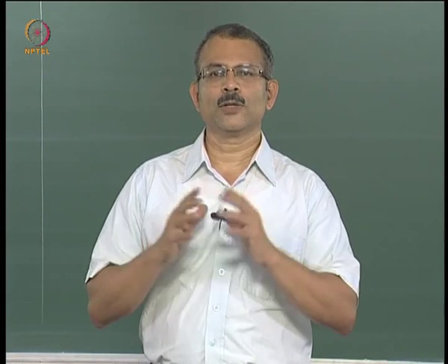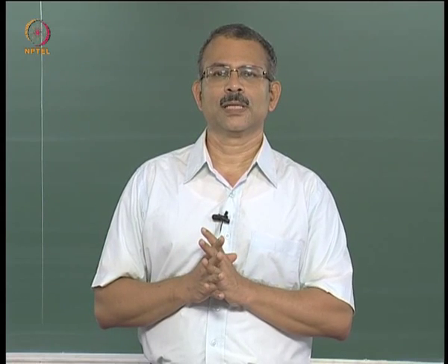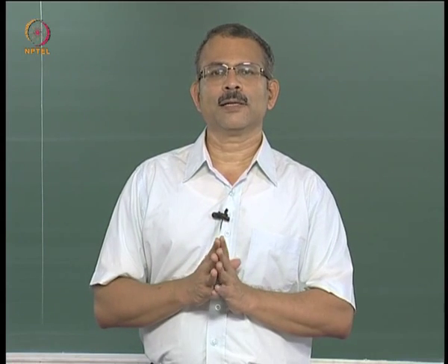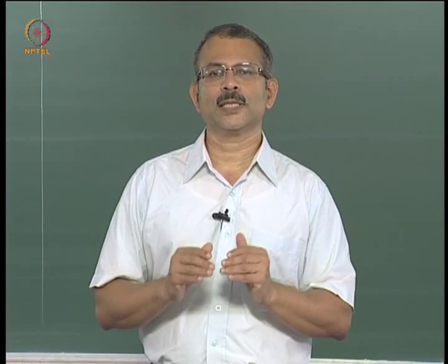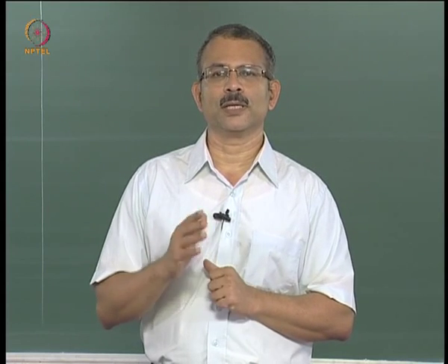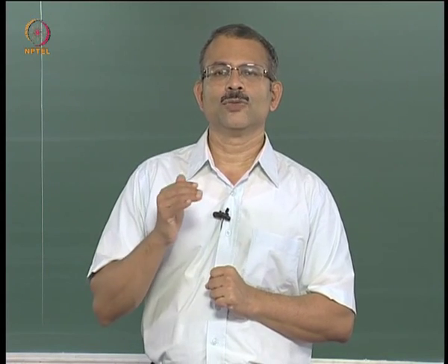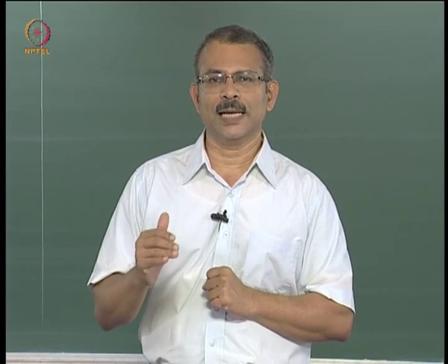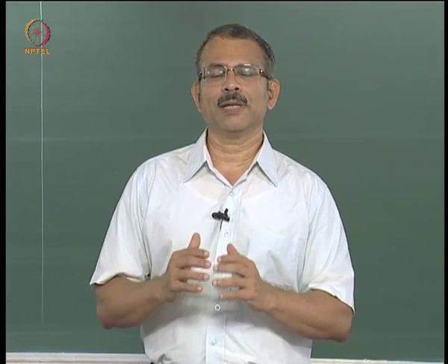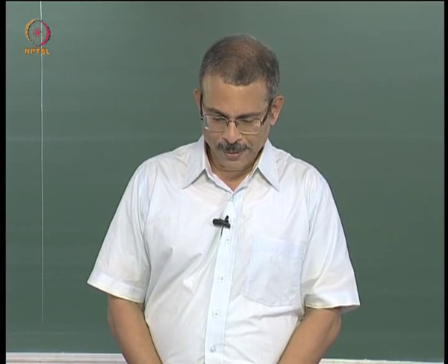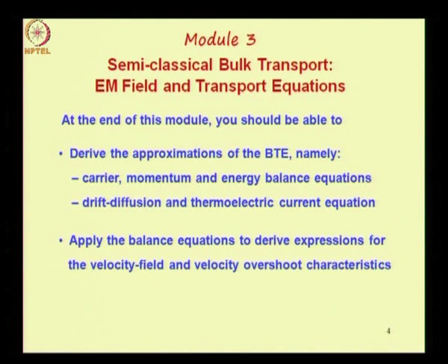So we are going to write down equations for this purpose, and in the qualitative model we have also discussed about the three mechanisms of transport: drift, diffusion and thermoelectric current. So we would like to write down expressions for these as well and show how you can derive them from fundamentals.